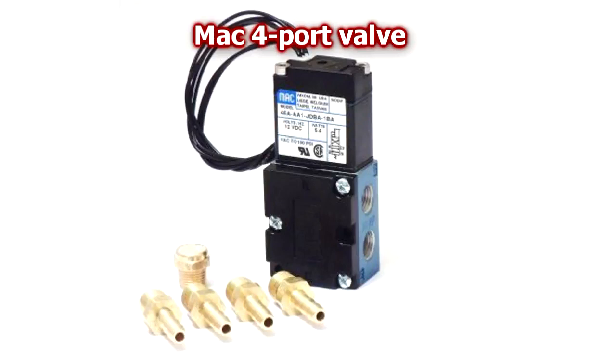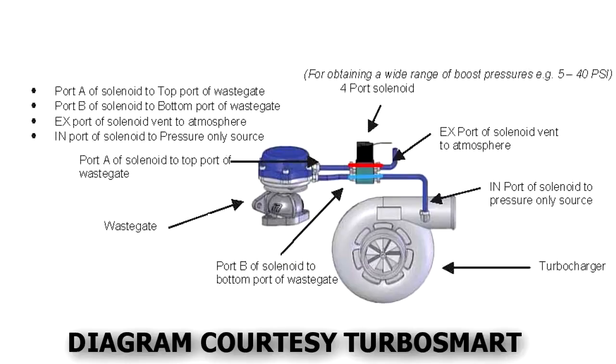There's a third connection type which I'll just describe. And this is basically a hybrid of the two that I said earlier. So you can think of it as having two separate 3-port valves. One of them goes to the reference port on the actuator, and the other one goes to the pressure port on the actuator. And they're configured in the same way that the previous two examples are described. So when the power is off, then the pressure port sees the boost pressure from the compressor, and the reference port sees the atmospheric pressure. And then when both solenoids are on, it's the other way around. So this way the reference port sees all the boost pressure and the pressure port actually sees atmospheric pressure.